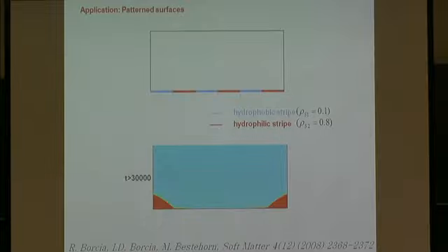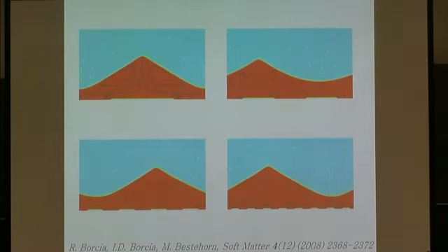And now, making the thin layers thicker, we can see the flow inside the layers. So here at the substrate, we have uncompensated forces, and this will lead to flows from hydrophilic to hydrophobic stripes. And this will maintain the layer wavy for longer time with peaks on hydrophobic stripes.